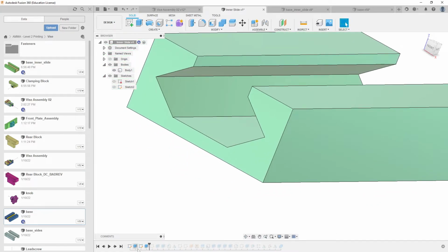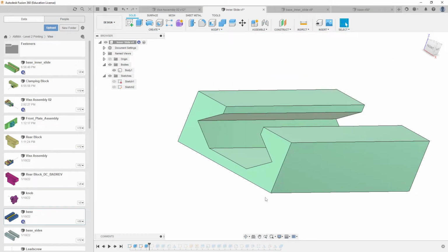Okay. Now I'm at a point where I have the cavity right there and the original thickness. Well, if I wanted to, I could bring this back even further. Now, you have to be careful, though, because if I change a dimension, you know how we've been using our projections a whole lot, right? If something that I did was a projection of an edge, then as I reduce the thickness, that's going to change the sketch on that face that has that projection, if you catch that, right? So we have to be very mindful of that, but it's also why we're doing this.